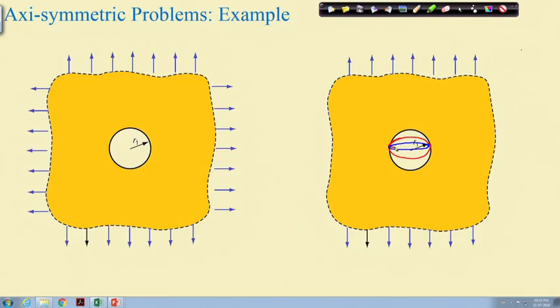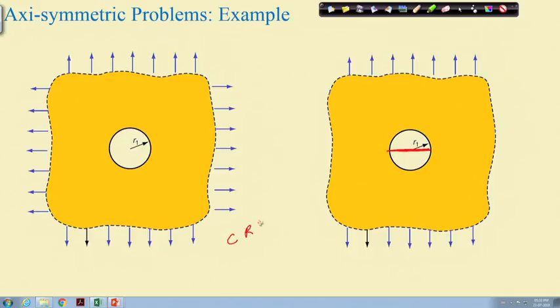or even smaller, or consider a limiting case where this minor axis becomes so small that the hole becomes just a line, and this line corresponds to a crack, or defects or material flaw. You see, this problem we will solve when we talk about the complex variable approach.